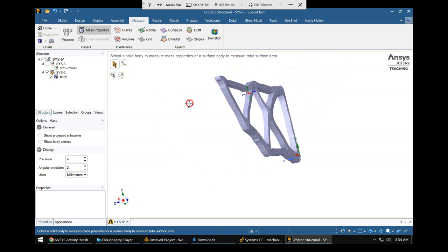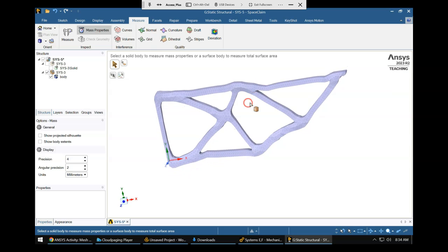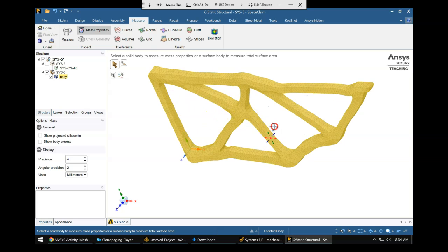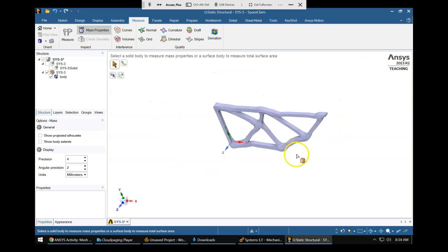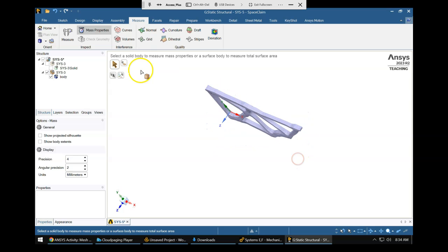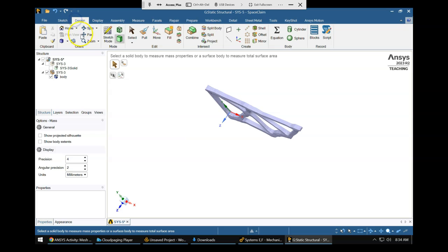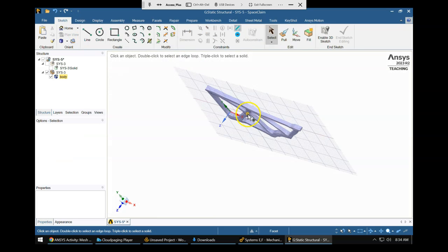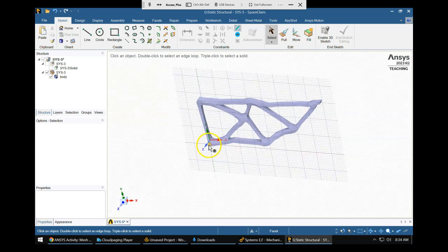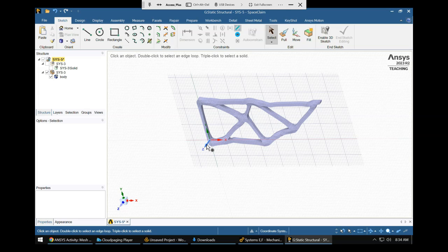All right, so last time we did a sketch, and we sketched on a plane and extruded it. This one we don't have that convenient plane. You don't need to do this step, but I'm just going to show you how you would do that even on this geometry. If I go into design and into sketch, before we tried to find a flat surface, but here we don't have it. But if I click on the Z plane, I'll automatically get the normal plane to that.